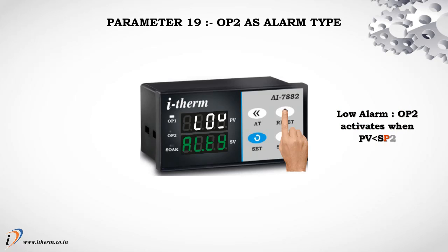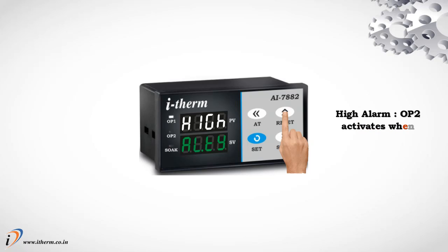Low alarm, output 2 activates when process value is less than setpoint 2. High alarm, output 2 activates when process value is greater than setpoint 2.